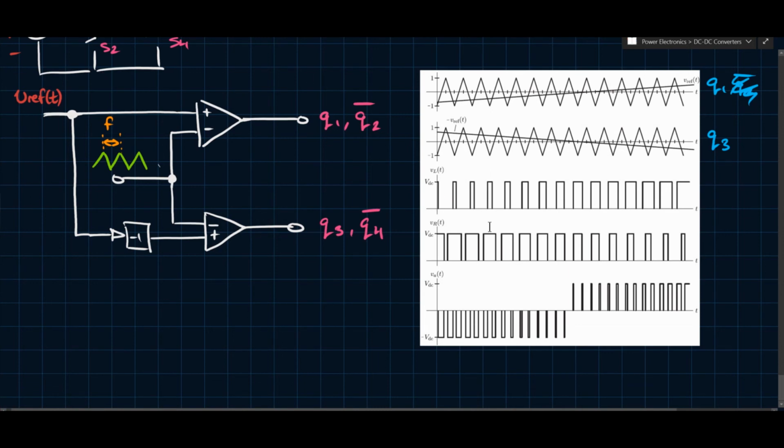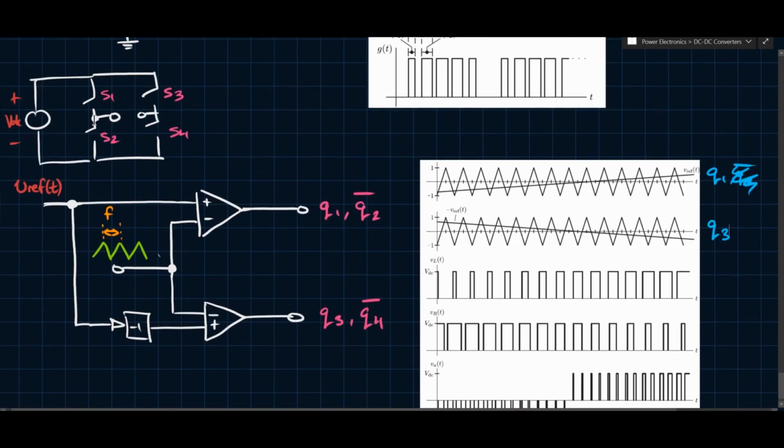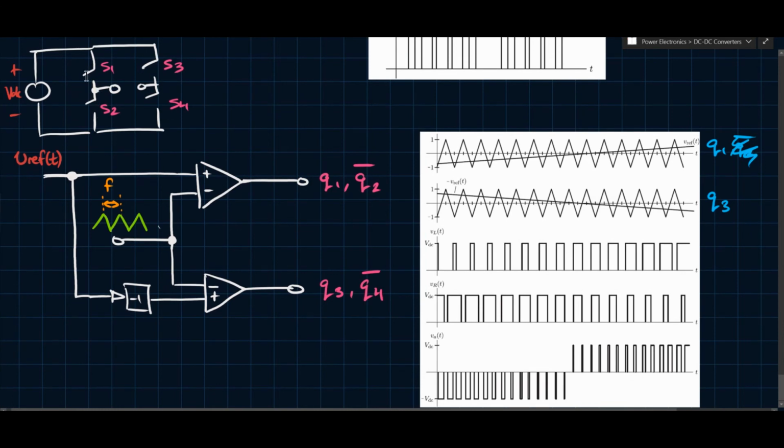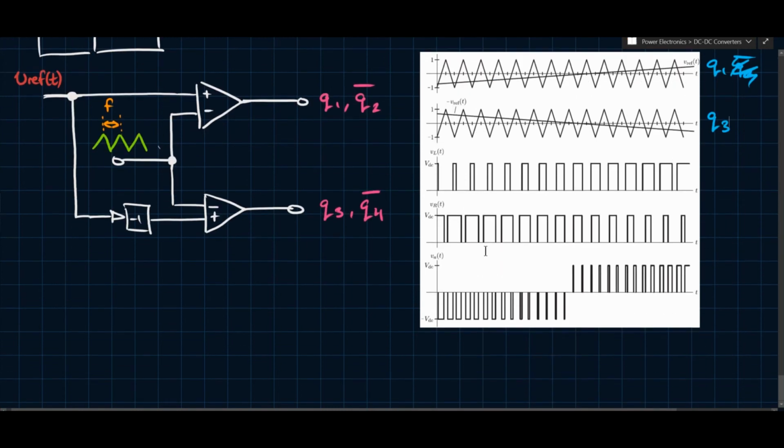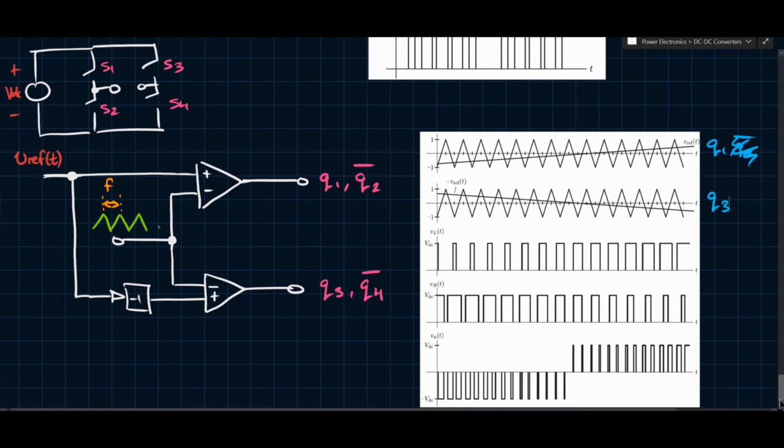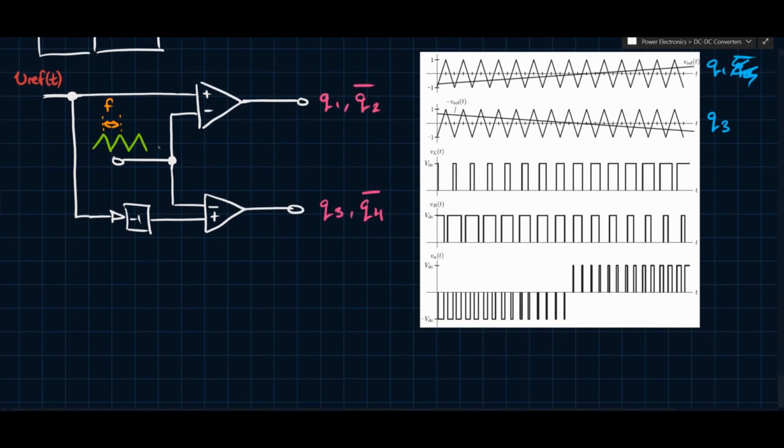VL and VR correspond to the midpoint voltages of these two legs of the converter relative to the virtual midpoint, which is sometimes considered neutral. Or we can call the point at the bottom ground and look at it that way. In any case, there are two voltages, VL and VR, the left hand and the right hand. The difference of the two is the actual voltage across the AC terminals.